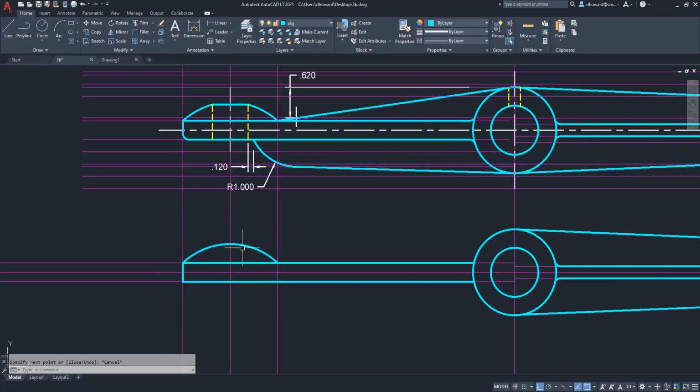The top of this arc needs to be flattened off. And it's flattened off where this hole is. This is the hole going through here that creates this flat. If that hole wasn't there, it would just remain curved like this, but it has a hole going through it. And that hole, its diameter is 0.75. So we would offset half that distance on both sides. So O, enter, 0.375 on both sides.